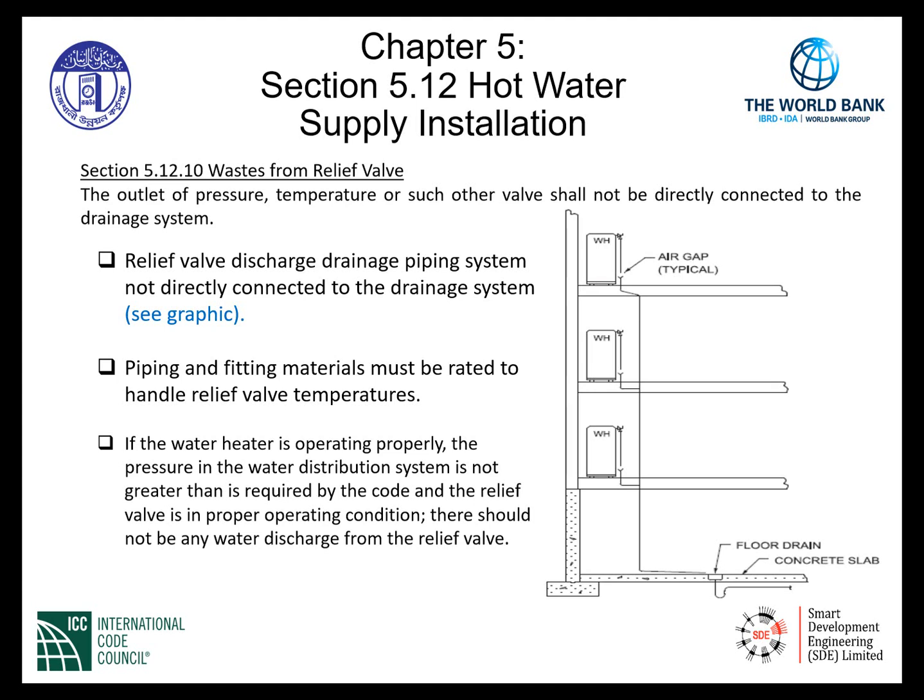Section 5.12.10, waste from relief valve. We need to make sure that the outlet of pressure, temperature, or other such valves are not directly connected to the drainage system. The relief valve discharge draining piping system, indicated to the right, indicates that there is a separate relief valve waste piping system. And in this case, it is not directly connected to the drainage system.